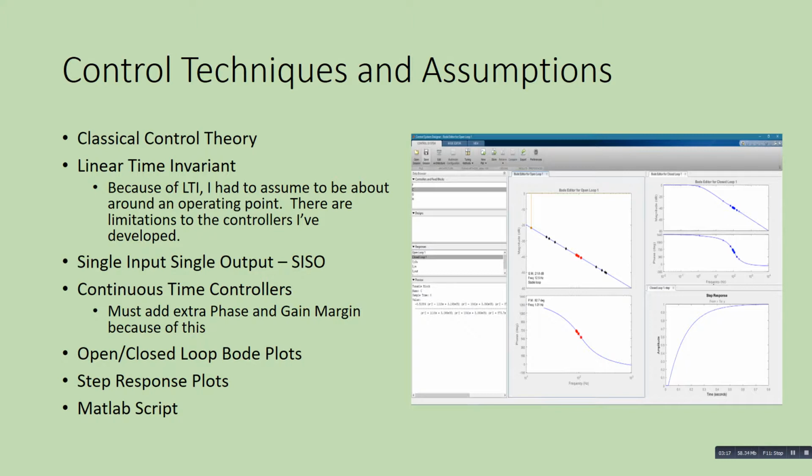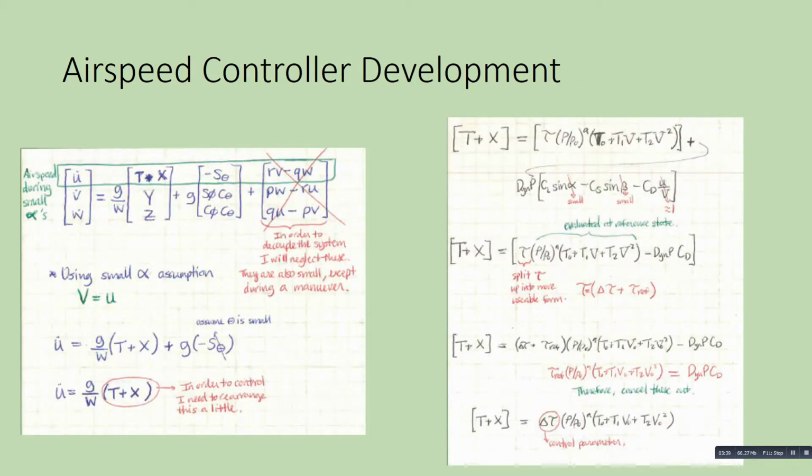I also used Control System Designer with Matlab to design the controllers, and that is a picture of it over here on the right. I used open and closed loop Bode plots, step response plots, and a Matlab script to develop my gains. I did proportional controllers for all my controllers just to simplify things as well.